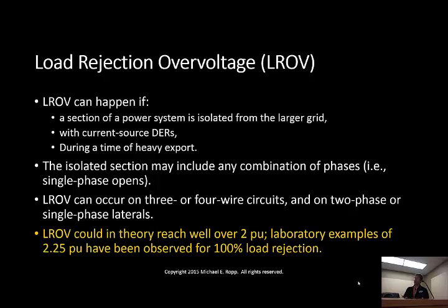Sort of the bottom line of the whole thing is that if you've got inverter sources and YG transformers, ground fault overvoltage doesn't appear to be a problem, which is great news. Unfortunately, you don't always have that case, so you've got to pay attention.